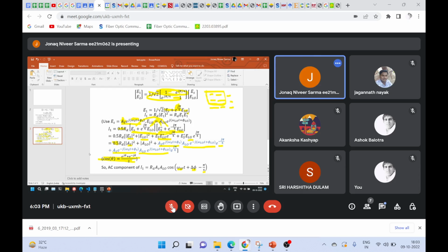We are only reading the photo detector properly, so you know what the current is. Noise power will depend on this. Just consider a thermal noise limited system, and noise power will remain constant if the bandwidth is not changing. That's all. Don't use your brain too much.